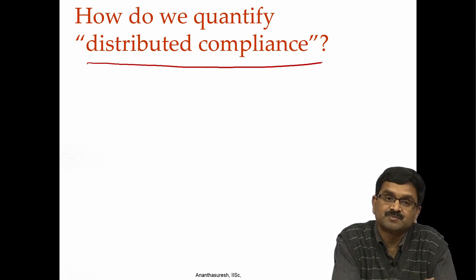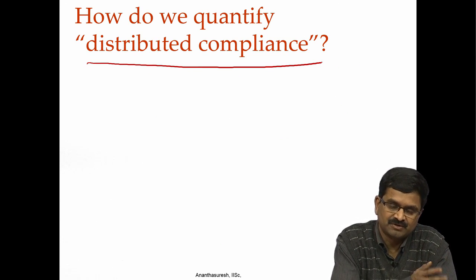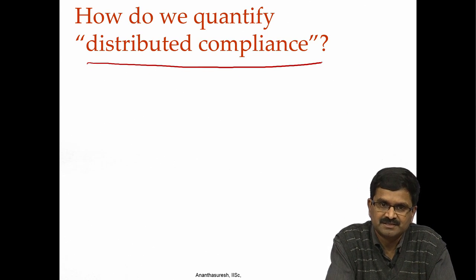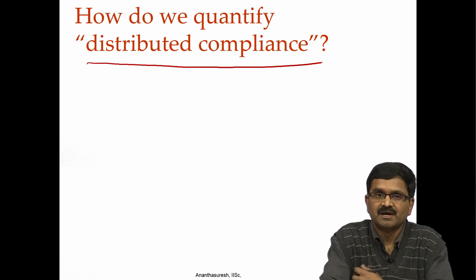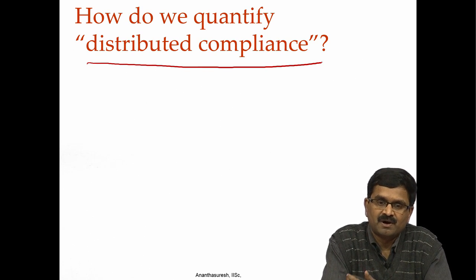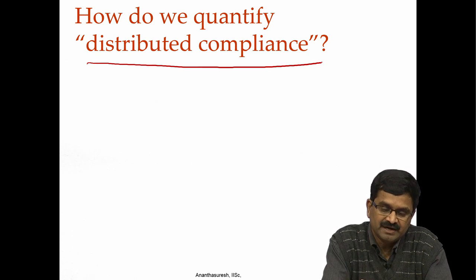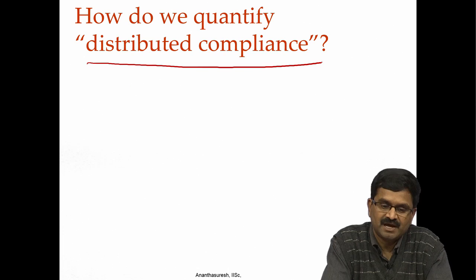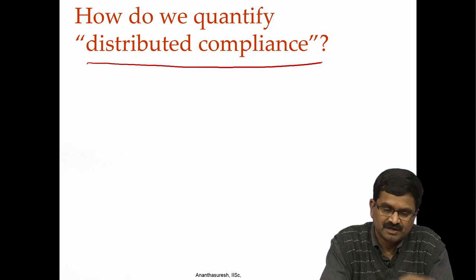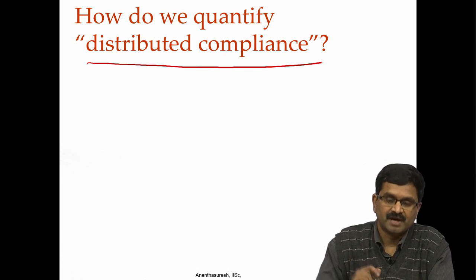In a structure it is possible, you can do that, that is what is called a uniform or fully stressed design. Is that possible to do in a compliant mechanism? Because in a compliant mechanism, strength or stress is not the criterion. The criterion is actually functionality. It has to move or give a motion in a particular way. If that is there, can you get uniformly distributed stress? That is the question that is to be answered.